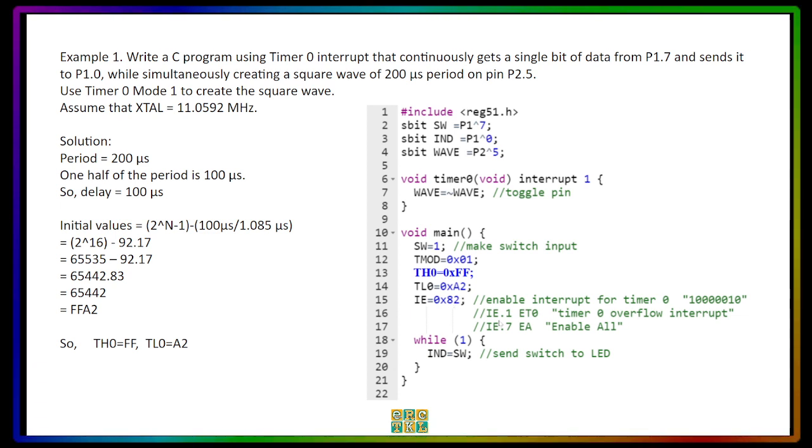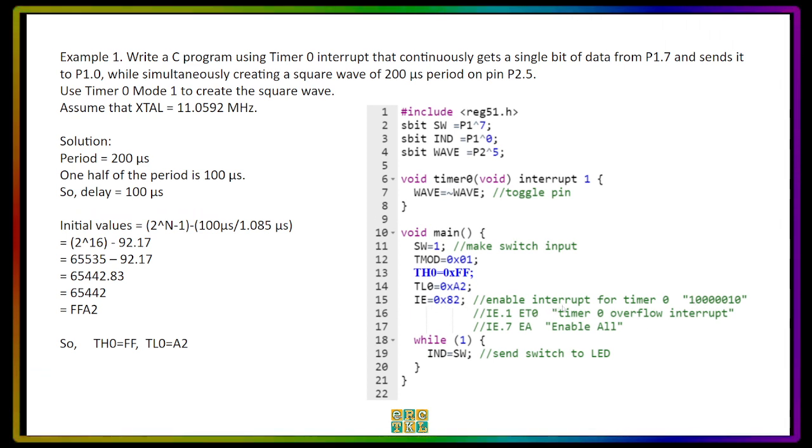So putting them together, this timer 0 interrupt enable will become 1000 0010. So this is what will happen. In other words, of these 8 digits here, one will go to EA and one will go to timer 0 interrupt.